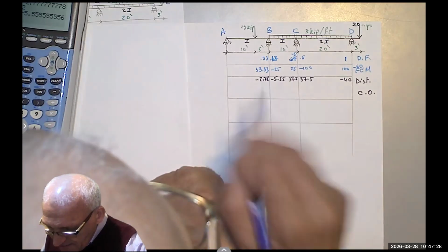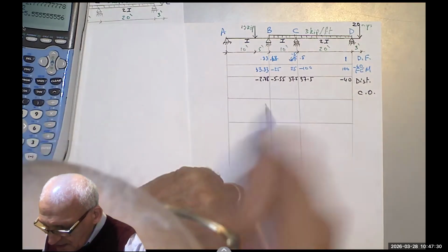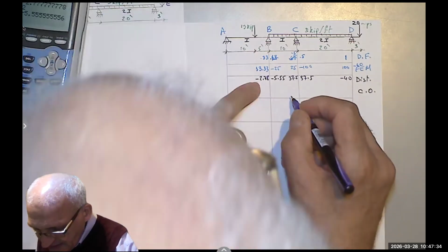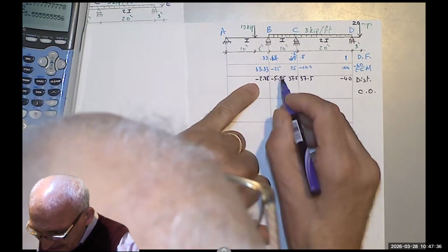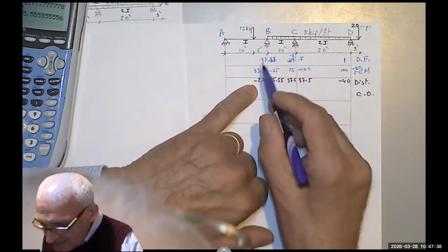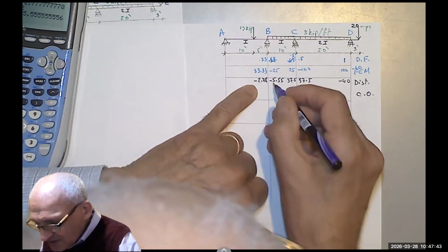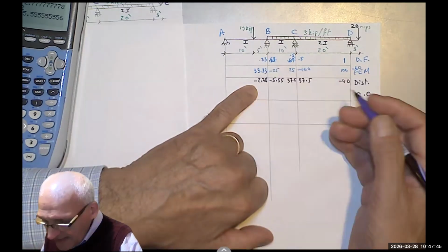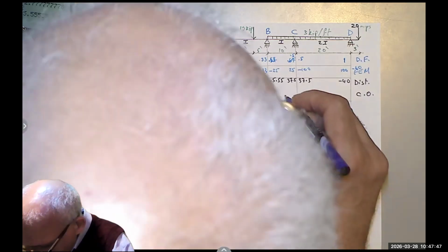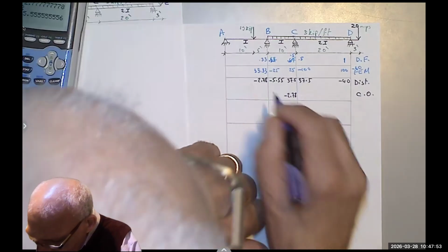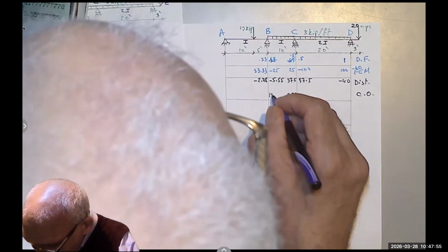This one will not give anything, but these two will reverse. So this would be negative 2.78. Notice the same as that, because it happened to be that the ratio is 1/3 to 2/3. So this is half of that, and you distribute half, or you carry over half. So this number will always come here as negative 278. But 37 and a half will give me here 1875.